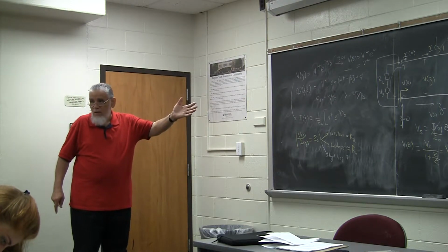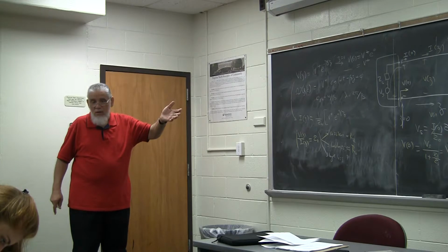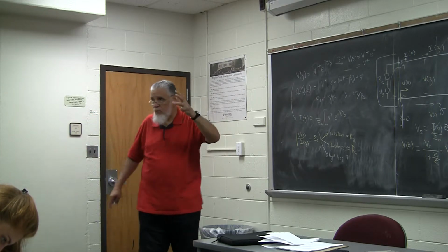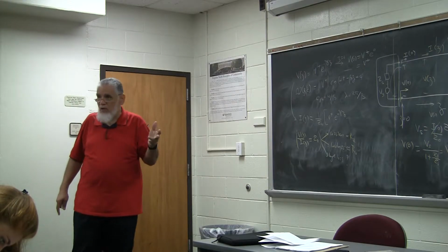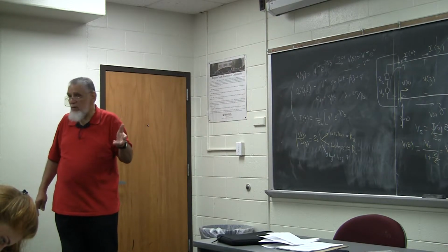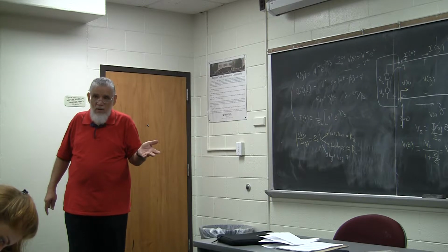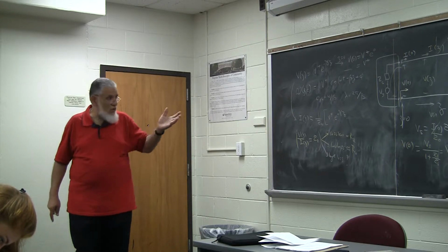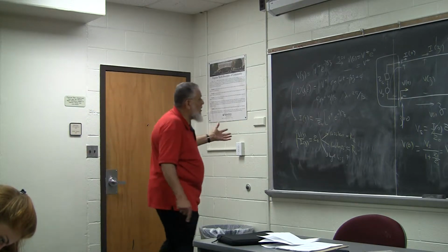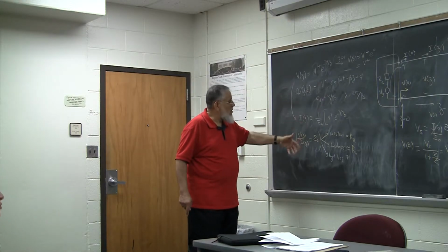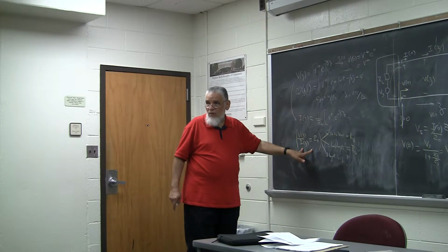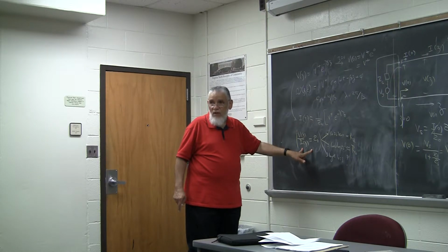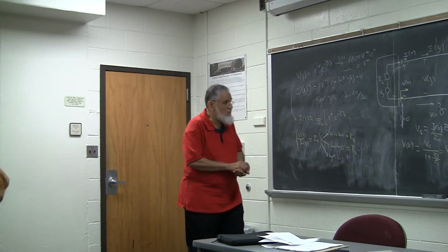So that's another definition. One definition was related to R, L, C and G. It's defined by the parameters of the line, the geometry, and the material. And the other definition, which is derived from the physics of the solution, is the input impedance of the line if it is infinite in length. There is a third definition, which I'm going to show you in a minute.